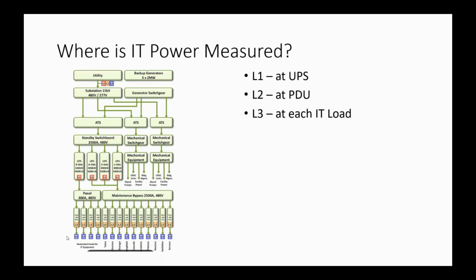And since these IT loads were highly variable, you couldn't go with nameplate ratings or even some derated versions of those and have anything that looked realistic. So you either were horribly over provisioned on power and cooling, or you ran the risk of being horribly under provisioned. So that's why these live measurements actually got into the products. It was not for energy savings. It was for being able to stay within the power and thermal envelopes of the environment. So that's why it's there.